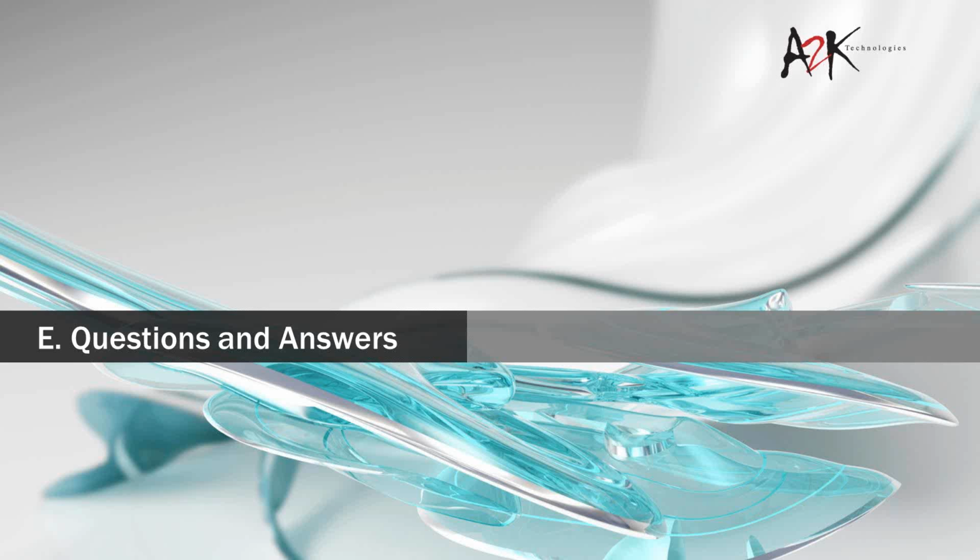So we covered off the basics of tube and pipe assemblies very briefly. You could see how we could create pipes using our automatic routing tools as well as using our manual routing tools. So for our tubing, we mapped where the route would go from our pump to our valve. Then we switched over to our cable and harness environment, where we showed how to create some wires between electrical connectors, how to map a segment between those connectors, and then how to route the wires automatically.